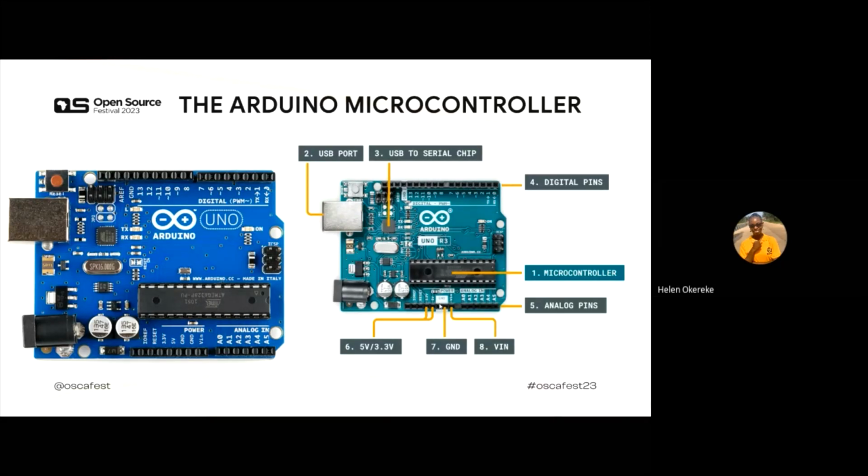So now there are 2 solutions to that. The first one is you solder them together, the whole negative pins, and then connect them to the Arduino GND. That means if you solder them all together, you have only one pin to connect. And you can just take that pin and connect it to one GND and everything is solved.